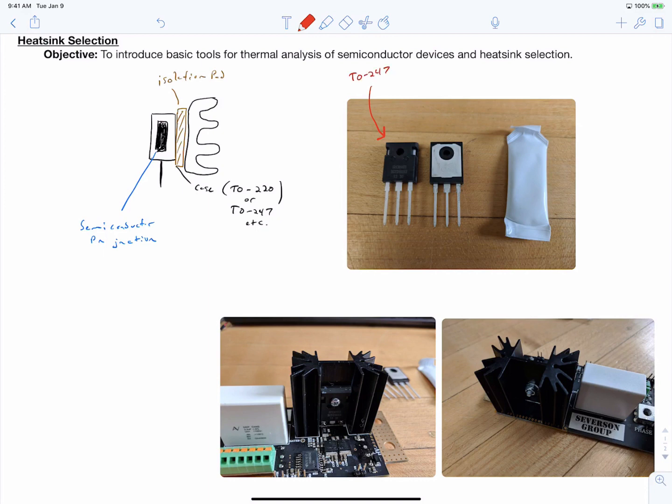We're showing the front side, and then the back side is here. You can see that on the back side, our case has this metallic area, which is where you are intended to connect the heatsink. So it's metallic, so it's very thermally conductive. Heat transfers easily through it without building up temperature.